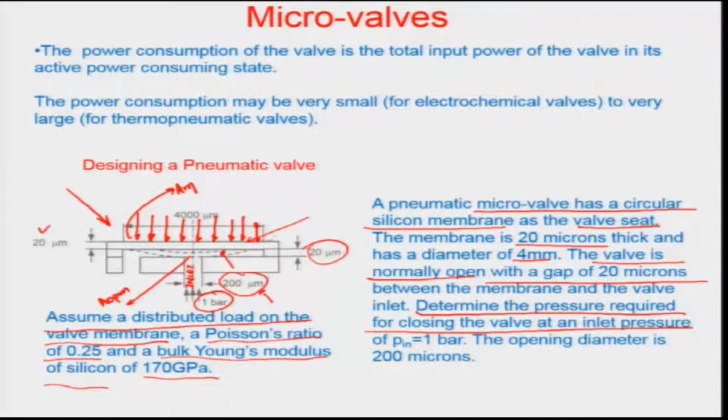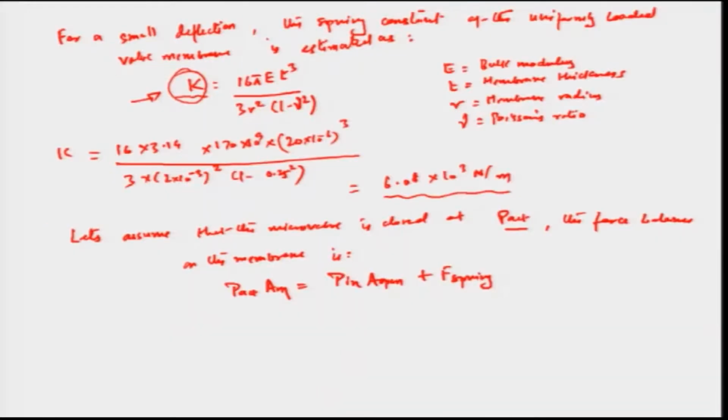you are holding the pressure inside this particular pipe, or in this particular inlet wing, and for that, whatever force is needed to bend the spring is going to give a reverse force, as if the spring were open and it would try to close. So, it will give exactly kx force, where k is the spring constant. So, k has already been calculated in this particular case.